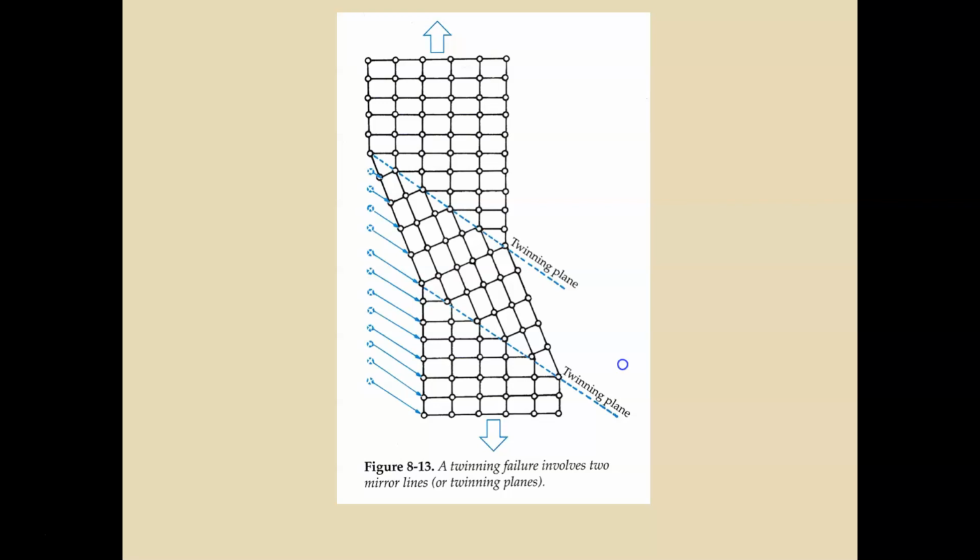The quantity of bulk plastic deformation from twinning is relatively small compared to slip. However, the real importance of twinning lies within the accompanying crystallographic reorientations. Twinning may place new slip systems in orientations that are favorable relative to the stress axis such that the slip process can take place. Twinning differs from slip in several respects.